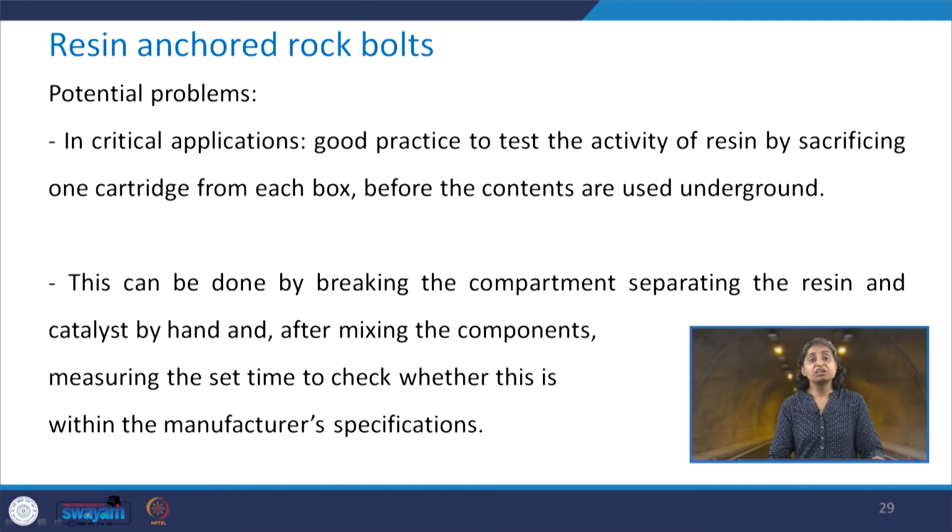Another potential problem is that when you have a critical application, it is always good practice to test the activity of the resin by sacrificing one cartridge from each box before the contents are used underground.